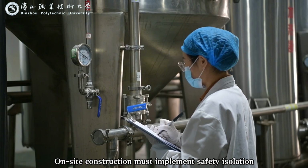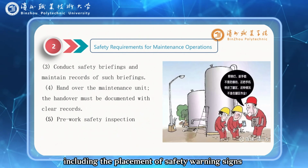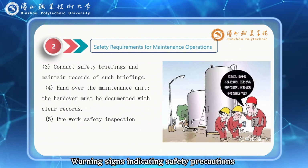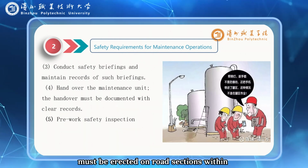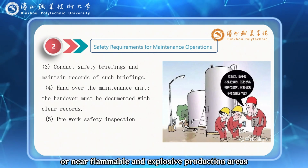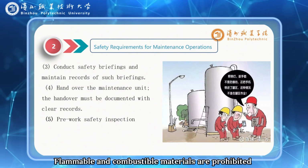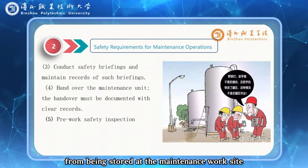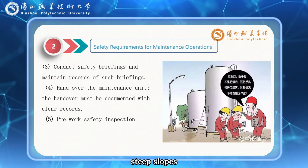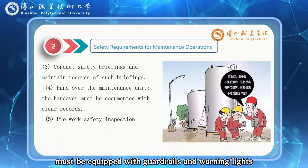On-site construction must implement safety isolation, including the placement of safety warning signs and caution tape. Warning signs, indicating safety precautions, must be erected on road sections within or near flammable and explosive production areas, tank farms, and warehouses. Flammable and combustible materials are prohibited from being stored at the maintenance work site. Pits, trenches, steep slopes, and other such areas at the maintenance site must be equipped with guardrails and warning lights.